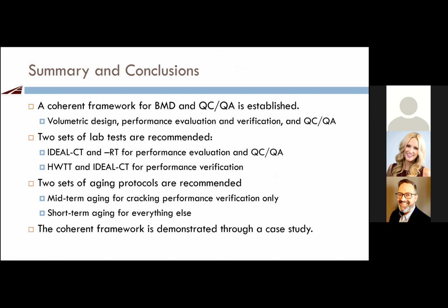So to sum up my presentation, we really have a coherent framework established. We have two sets of lab tests. I do CT and RT for performance evaluation, the QC/QA, and Hamburg, and I do CT for performance verification, with midterm aging for cracking performance verification and short-term aging for everything else. And it demonstrates this process.